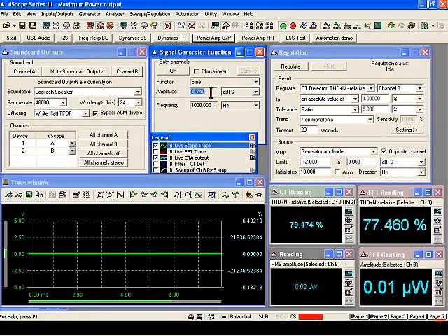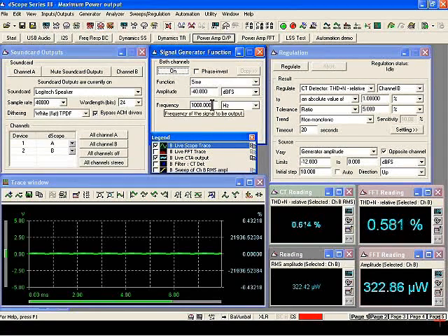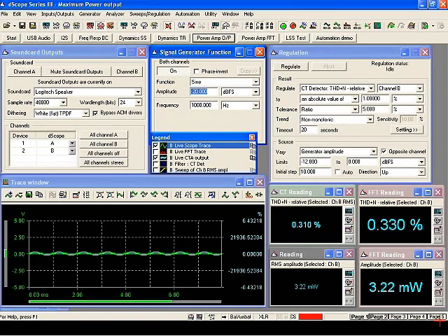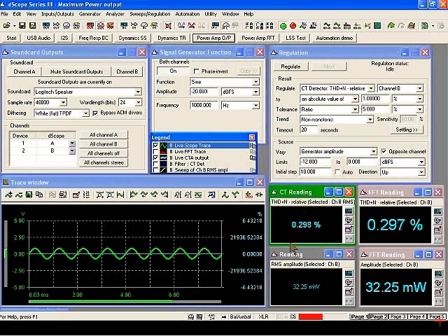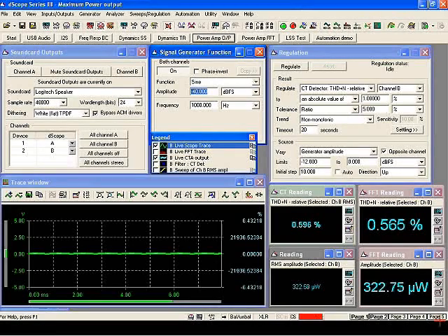Now, what I could do here is turn on my signal generator, starting with a relatively low amplitude to begin with, and I could try dialing in different amplitudes here, attempting to find the point where my THD plus noise reaches a predefined level. Now, for the purpose of most engineers, we would talk about either a 1% or a 10% THD plus noise limit, that being the limit where we say that we are going to obtain no more useful output power from our amplifier. We have reached the onset of clipping, and therefore that is how we quantify our maximum output power.